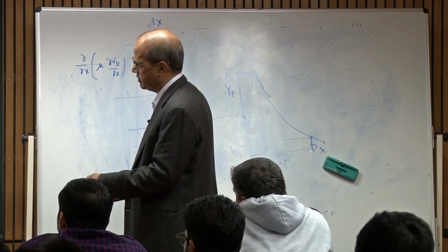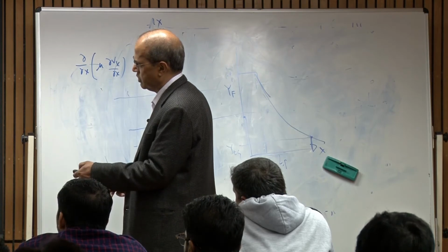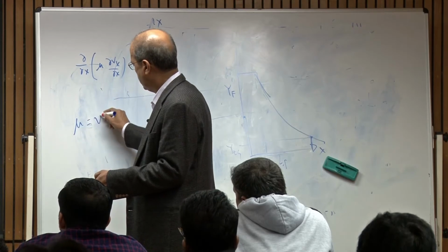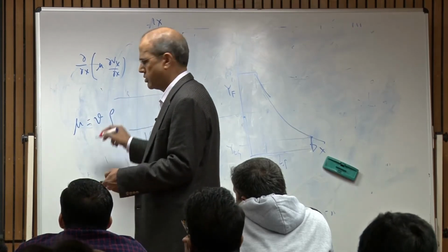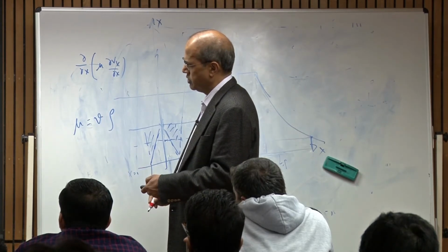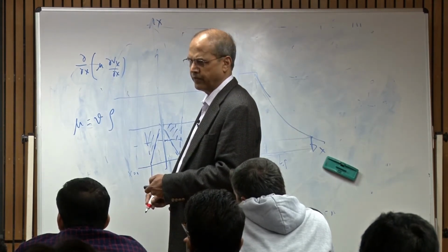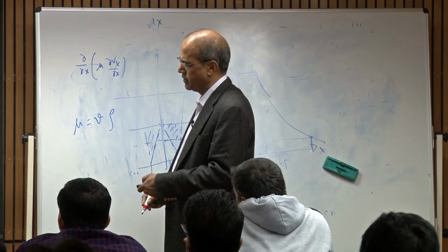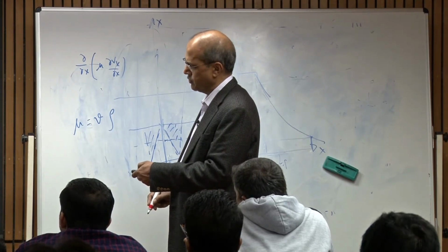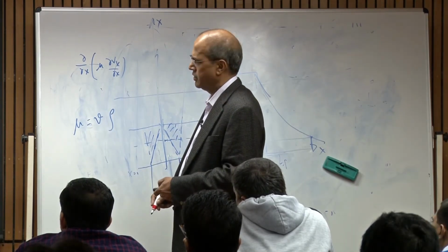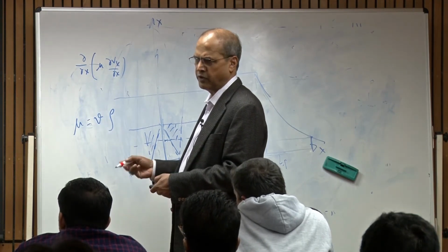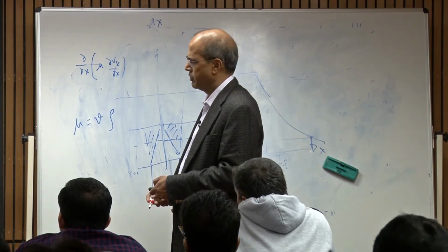And if you neglect this, you can see this is replace this mu by nu times rho. So, here you have nu, and this equation you have d. If the Schmidt number is 1, okay, they become identical when you neglect the buoyancy force. Okay. Then the solution of this equation will be identical to the solution of this, provided the boundary conditions are also same. Okay.